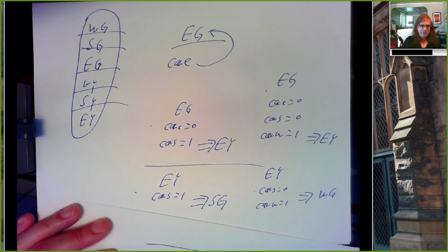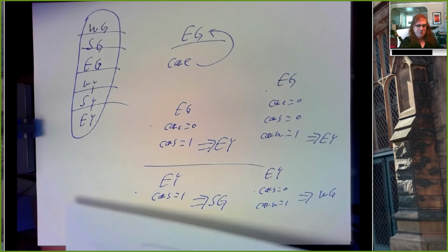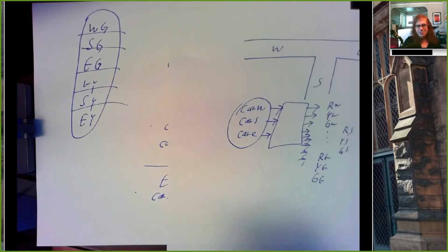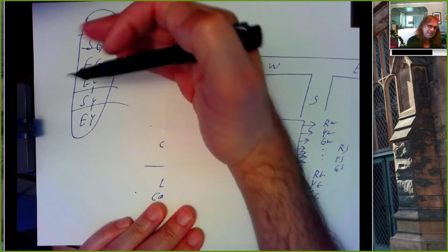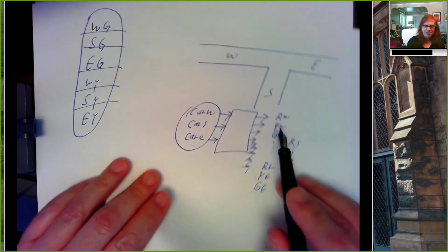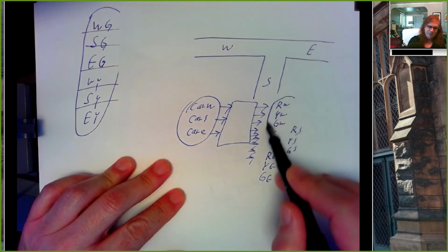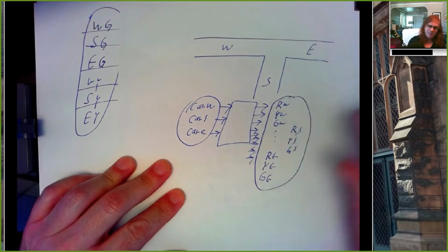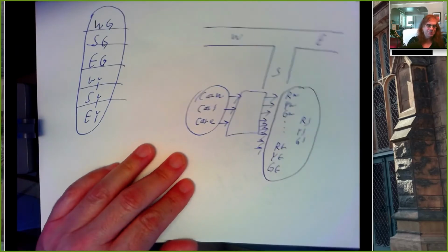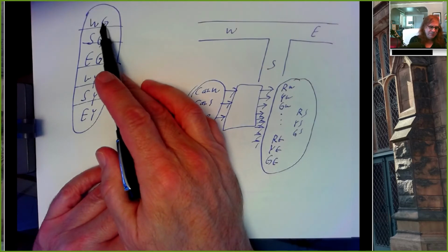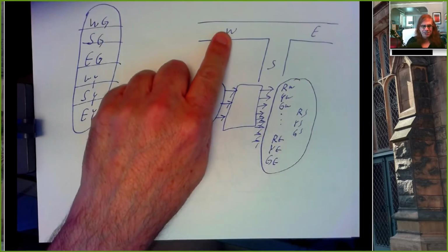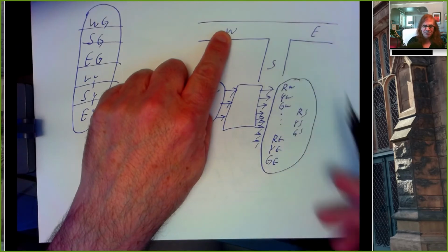And that'll give you those nice controlled transitions. And then outside of all of that, once you understand how to move from state to state, you need to actually set up these lights. But these lights you can set with a series of assignment statements. If I'm in the west green state, what does that mean? It means I want a green light here, red here, red here.